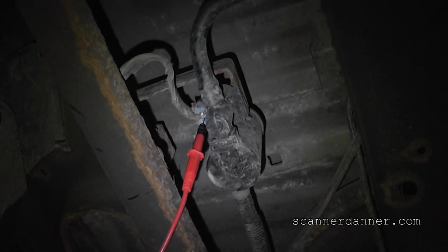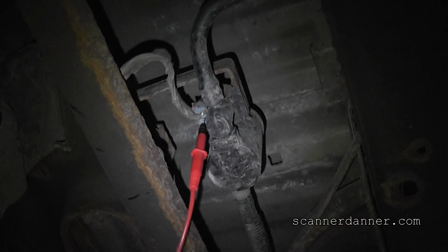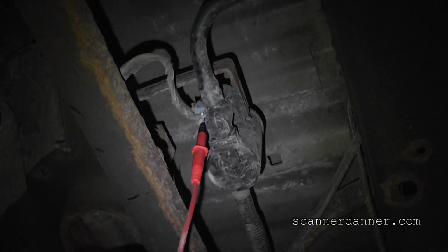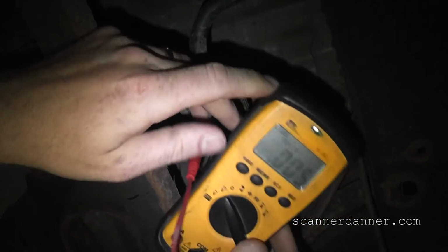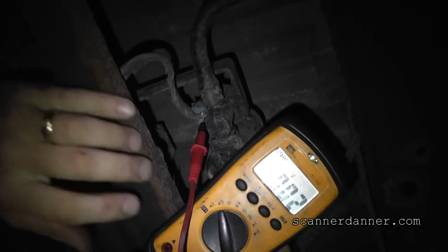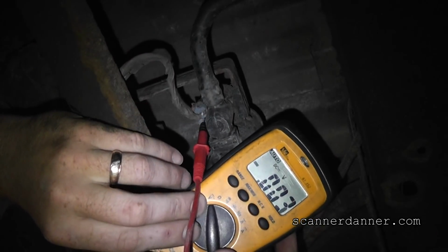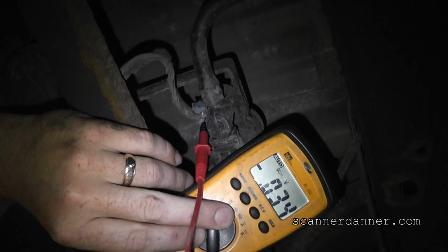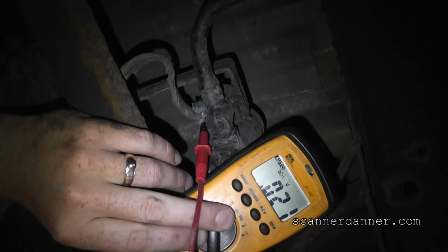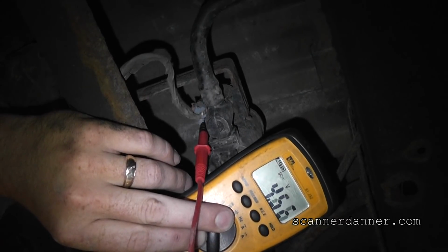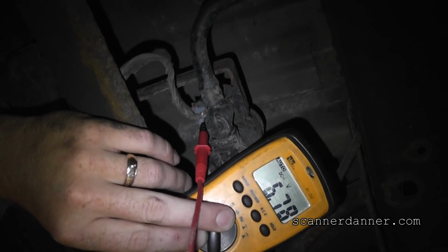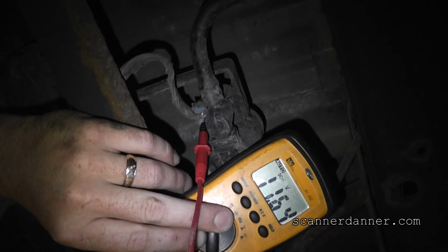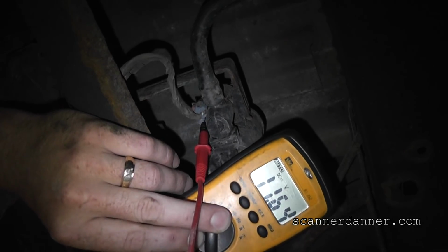So the first thing I'm going to do when I take this measurement is watch my meter. I think I can show it to you. Can you guys see the numbers on that? Or is that light? How about that angle right there? All right, so when I connect this ground, I'm going to wiggle it and see if I get my 12 volts. I'm just scratching an area with the connector. And I have 11.6 volts in this location.